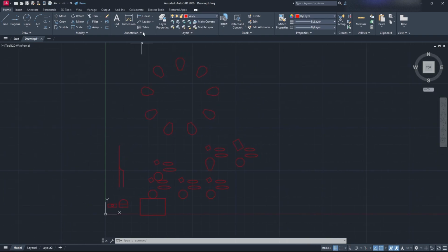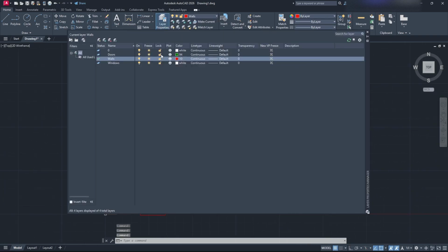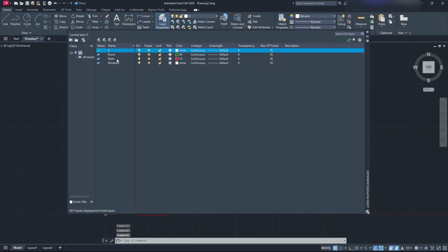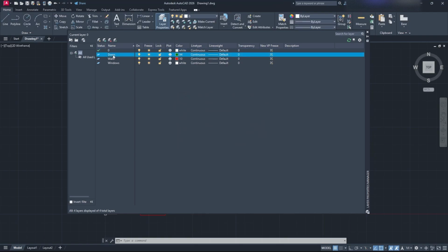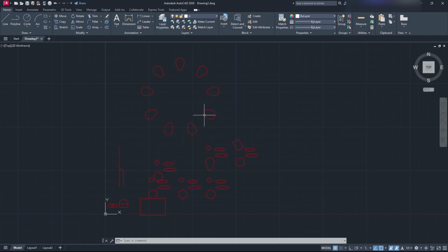So I'm just going to go back to there, and that's how you deal with your layers, and that's mostly how you deal with layers. So you can create new, freeze, delete, and select. So again, when you're trying to freeze a layer, you do not want to be on that layer because it will just copy it, make a new layer, in the hope that you'll select that and it'll be able to freeze it. But don't do that. You want to be off that layer. You also don't want to draw in the 0 layer because it's the base layer. You're always going to want to draw in different layers that are not 0, 0 is just the base. So just keep that in mind.